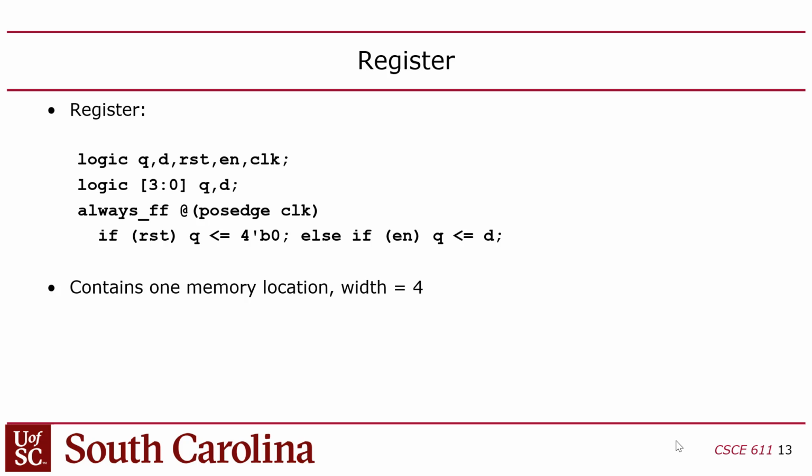But on the other hand, if you want to read the inputs from the switches, use the same instruction, CSRRW. And in this case, the 12-bit immediate is going to be 0xF00. And then the RS is a don't care, and the destination is whatever register you want to transfer the switch state into, right?